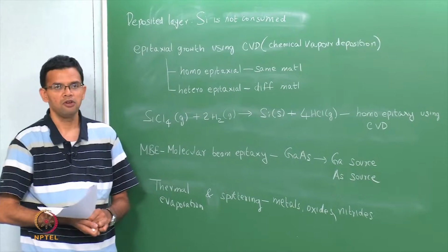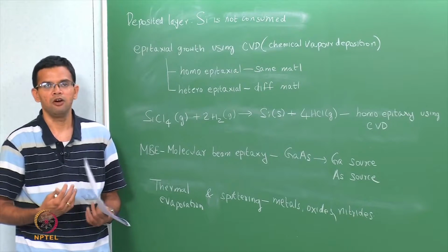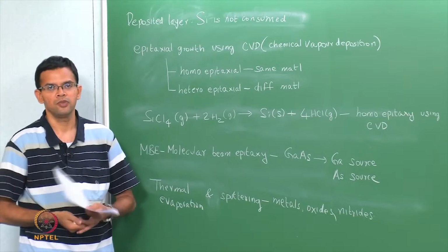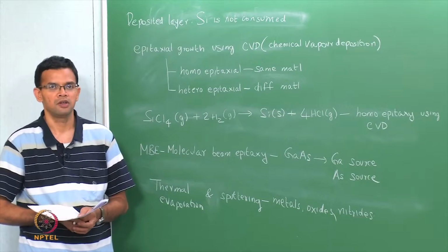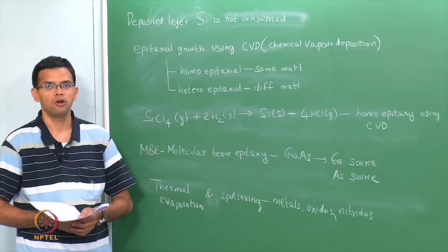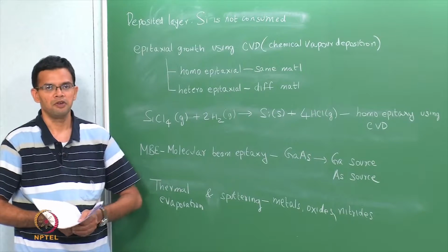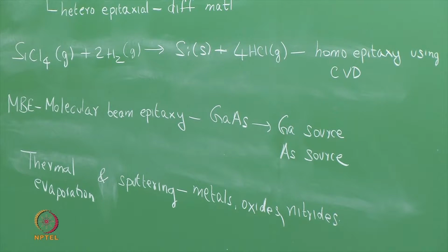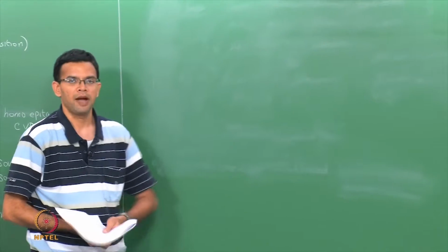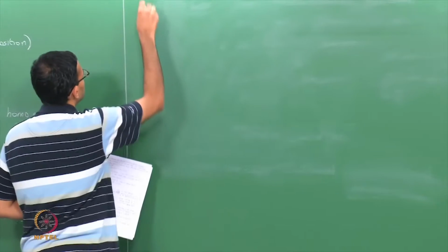So, first we have looked at layering, which is a way of adding a layer of thin film onto your substrate, the substrate here being the wafer. The next most important part of the wafer fab operation is the lithography step. So, the next step is called patterning, another name for it is lithography.